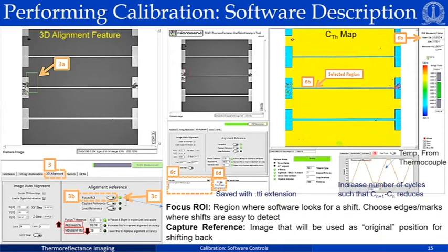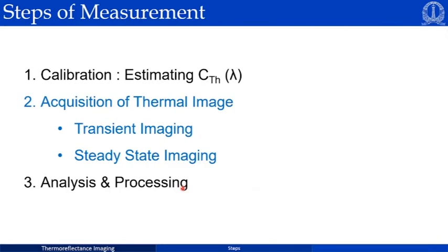How can you do that? You can monitor this in the ROI history. It plots C value versus run number, and once the criterion of Cn+1 minus Cn being low is achieved, then you can save your measurements. If you click on save every cycle and give your saving path, then all the measurement cycle images would be saved in your desired folder.